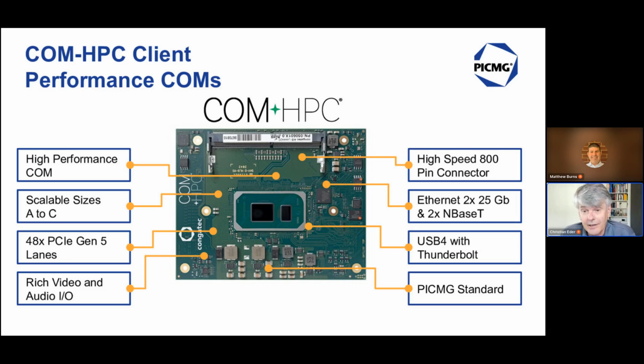Again, also 800 pins, but let's say the distance between the two 400 pin connectors is slightly different to the server, so they cannot be mixed that easily by accident. Less Ethernet, but still featuring the 25 gigabit Ethernet lanes, which is important. And it does support, just as an example, USB 4, and it's also PICMG standard.